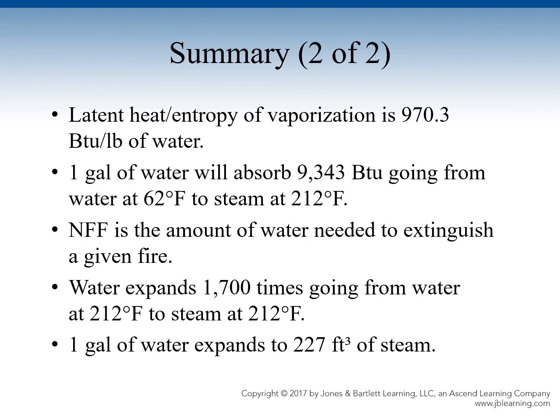The NFF, or the needed fire flow, is the amount of water needed to extinguish a given fire. So this is where I want you to remember again, gallons per minute puts out fire. I want you to think of GPM. Gallons per minute is what extinguishes and puts out fire, because the truth is we can have water in motion through our pump, but if we are not applying enough gallons per minute for the volume and size of fire that we have, we're not going to achieve our goal of extinguishment. We have to meet that amount of water to put the fire out.